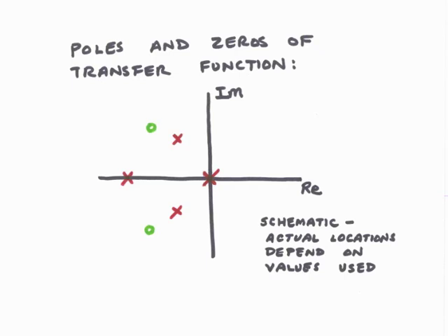What do these poles tell us about the way the system will respond to an impulsive force acting on mass m2? We have one pole at the origin, and so the characteristic mode associated with this will be a step. And then we have two complex conjugate poles. The characteristic mode associated with these would be a damped sinusoid.